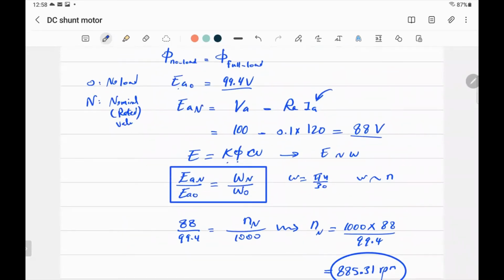The second thing, the torque. So how can you find the torque? I told you two important relationships in a DC motor, whatever the connection is, series, shunt, compound. One for the voltage and one for the torque. We said that the voltage is equal to K constant times phi times n, proportional with the speed. The torque is proportional with Ia, with the armature current.